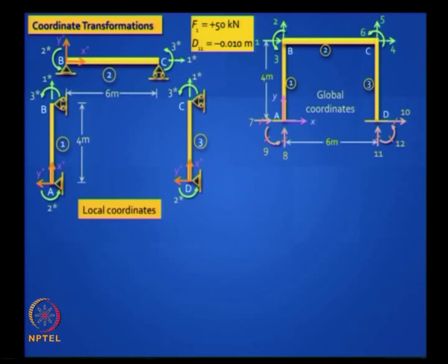Now you are dealing with 3 elements, and each of those elements has 3 degrees of freedom. 1 star corresponds to the axial degree, 2 star corresponds to rotation at the start node, 3 star rotation at the end node. Okay. And you can choose your start and end as you wish. In this case you can see that for elements 1 and 3 I have chosen the start node at the bottom. Okay. You have to generate this matrix, give it a shot.